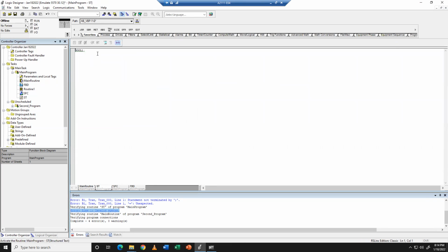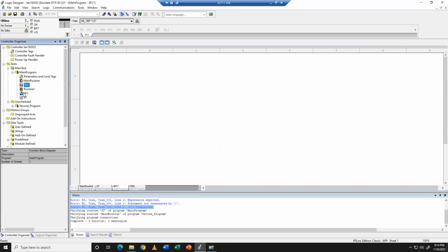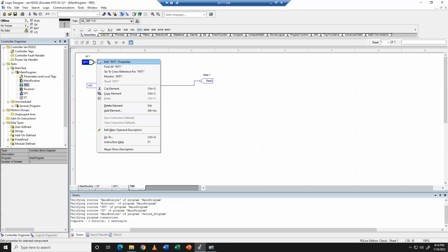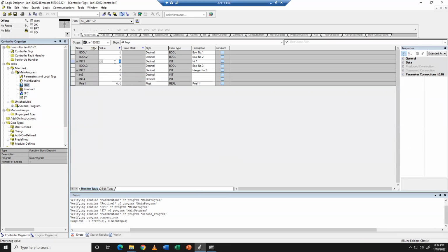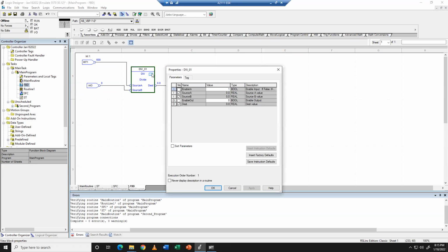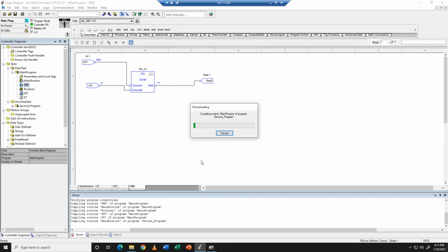Invalid syntax. Yeah, the structured text doesn't like my syntax. Great. And this is all gibberish because I didn't add anything. So nothing's happy. But you're fine. Wonderful. Why isn't that running? Oh, I'm not online. If you're not online, the code won't execute.